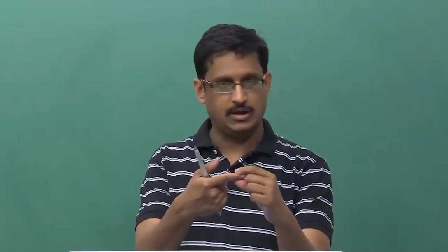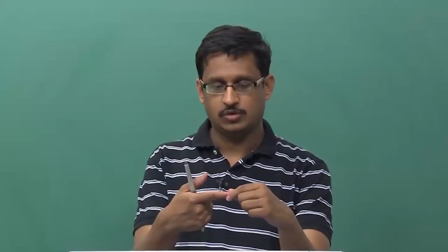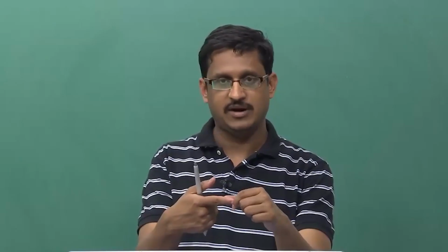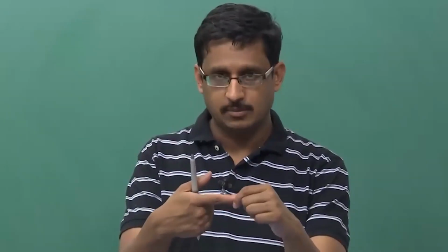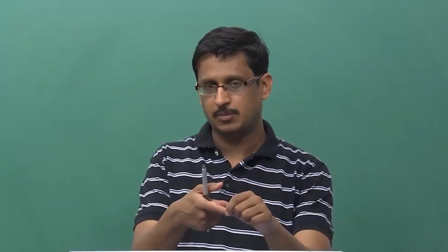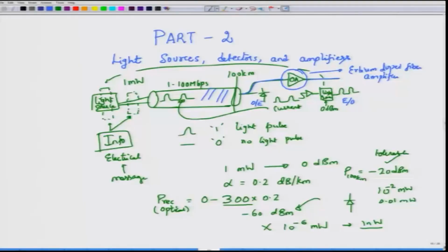So, you could just connect two fibers and light would propagate into the second fiber, which is doped with an atom called erbium, or erbium ions as we would call them. By properly adjusting the optical pump to this erbium doped fiber amplifier, you could get any gain that you want that could offset the losses in the fiber, and out of the erbium doped fiber amplifier would be the signals in the optical domain. So, you did not have to do an optical to electrical and electrical to optical conversion. At every span you could simply place an erbium doped fiber amplifier and almost be done with it.